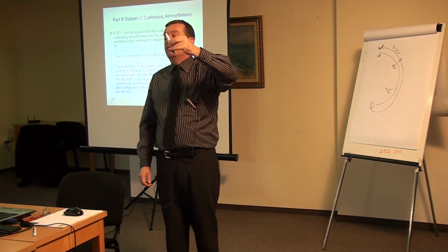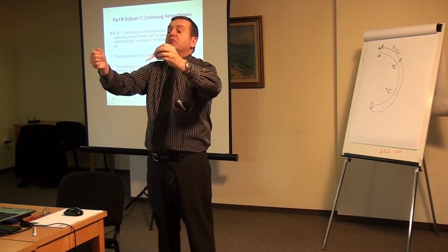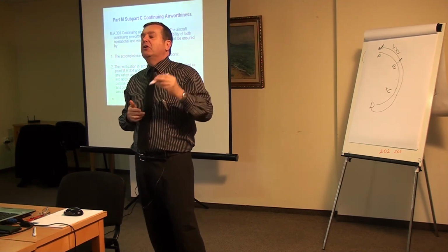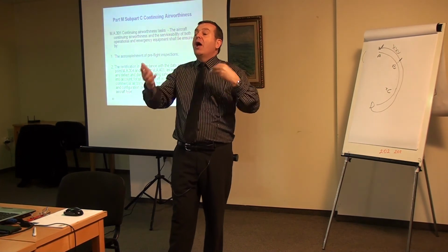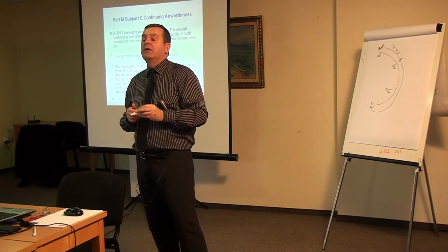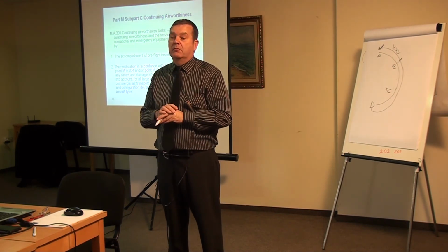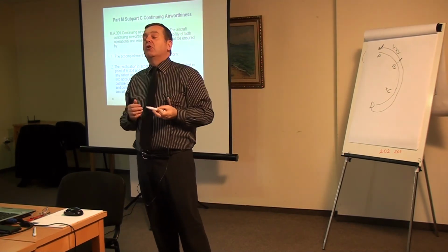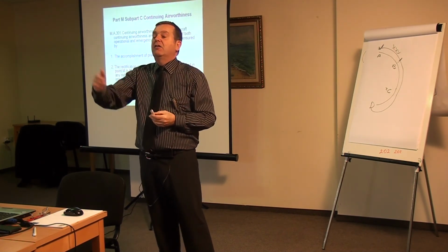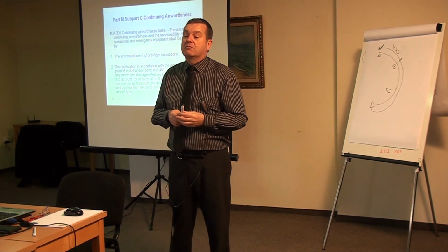In fact, even though he was at 500 feet, his only chance was to push the control column forward and head to the ground and get some speed up. He didn't. And it's very easy for me as a maintenance guy to make these comments, because with hindsight we're all very aware. But again, it's back to training, competency, knowledge, understanding. Any pilot that practices that in the simulator will never have it happen to them. However, when he pulled the control column back, the airplane speed reduced even more, and the airplane fell out of the sky and crash landed, broke open the airplane, killed the pilots and several passengers.